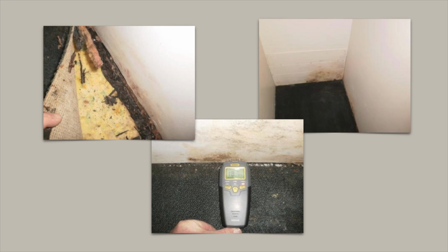Water trickling down the interior foundation wall. Water pooled on the basement floor. The bottom course of concrete block walls are darker due to water saturation. Damp, humid air, or musty smell. Evidence of condensation on cooler walls and concrete floor during the summer months. Evidence of mold and mildew.